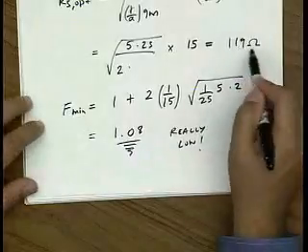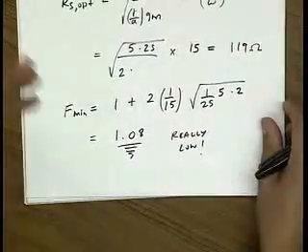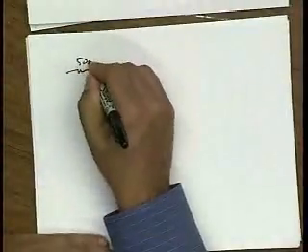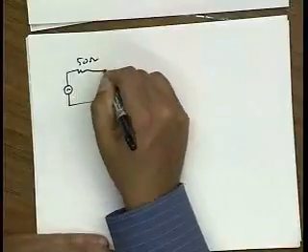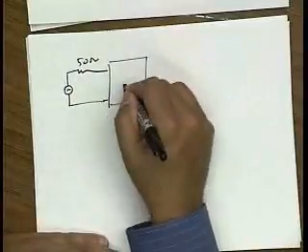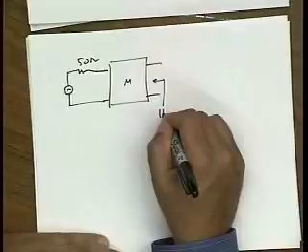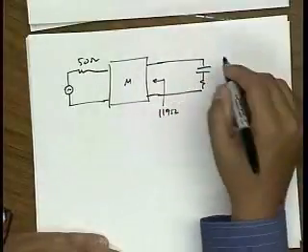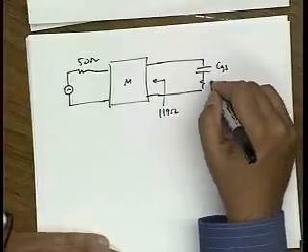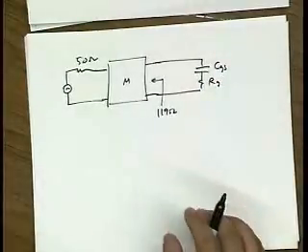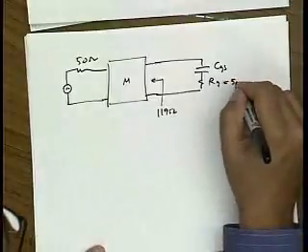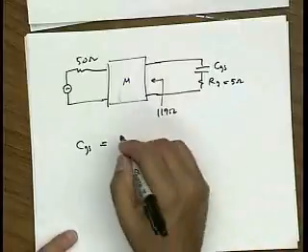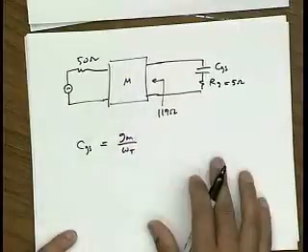The problem is that we have to make our source 119 ohms. Okay, that's no big deal. I have a 50 ohm source, and I go through a matching network, and looking out here I see 119 ohms, and then I go into my transistor, and my transistor has CGS here and RG here, right? So RG is about 5 ohms, and CGS I can calculate from the omega t of the device. It's GM over omega t.